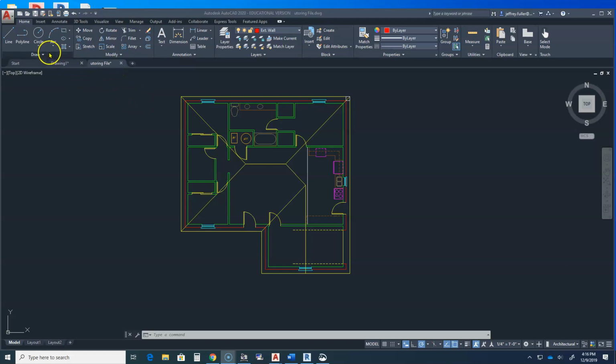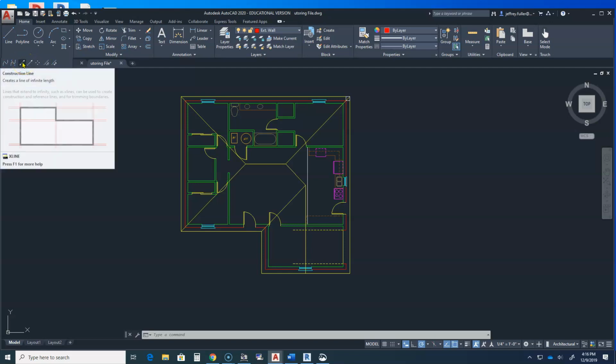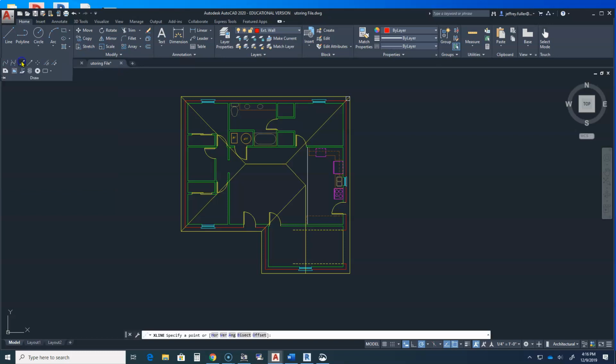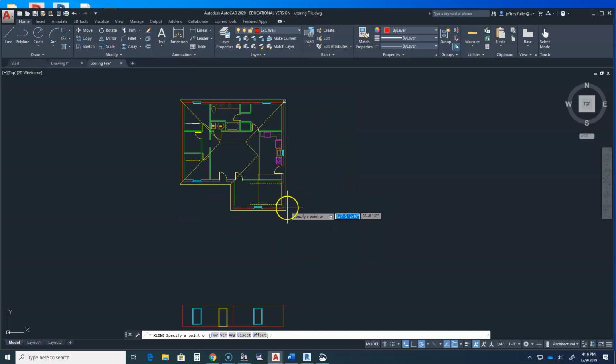In the Draw panel, click on the Draw drop-down menu. You can hover over the tool icons in the menu and an identification and instructions will eventually pop up. You want the construction line tool just like you used before when you were drawing the elevation views of your walls. Work with one view at a time and draw construction lines that mark all the geometric features such as the ends, corners, ridge lines, and apexes.